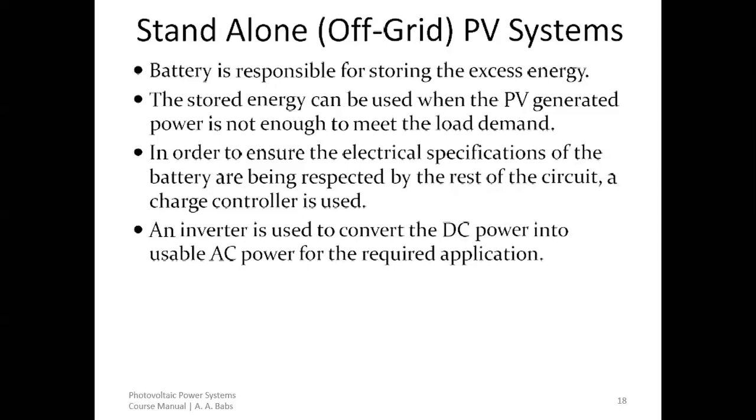The first place is the battery bank, where the electrical energy is stored. The second place is the standalone inverter, where the DC energy is converted to AC energy that is eventually transported to the distribution panel and then to the user's AC load. The third place is to transport DC energy directly to the DC loads so that the user can supply his or her DC loads with the energy coming from the PV power plant. So those are the 3 places the energy goes to. And the battery itself is storage. It stores electrical energy.